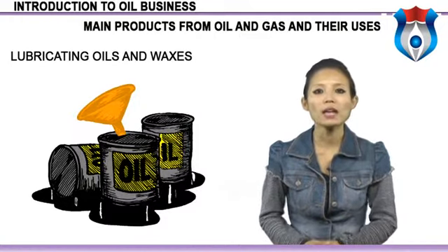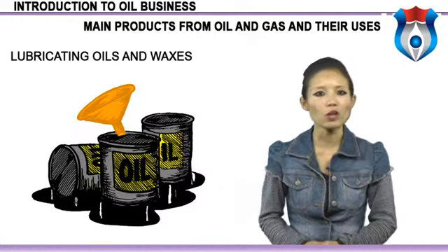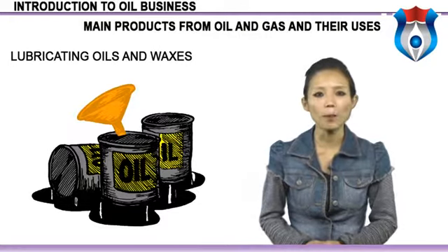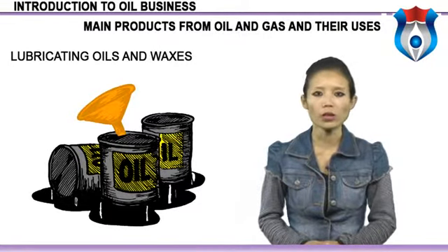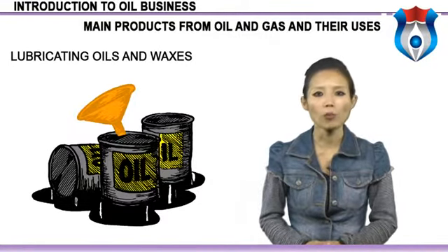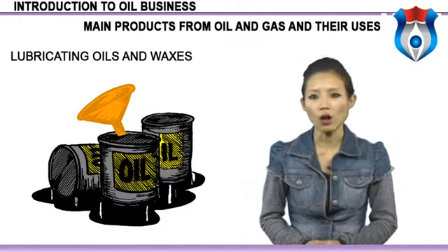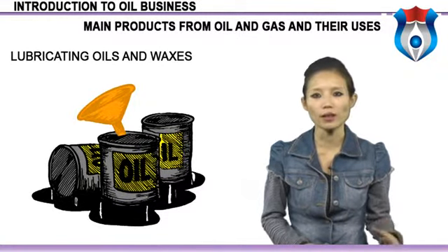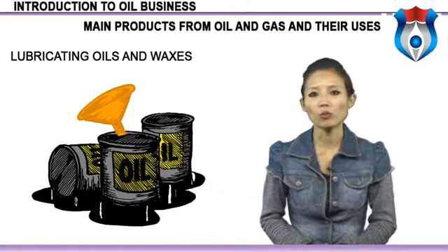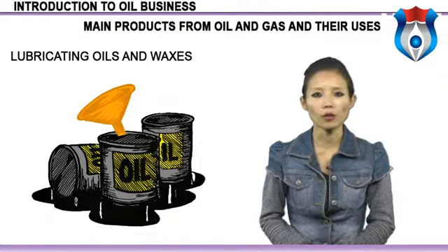The pour point is defined as the temperature at which the oil stops flowing while cooling down. Straight chain paraffins increase the pour point, while branched chain hydrocarbons, cyclic compounds and aromatics lower it. Waxes can be removed with solvents to lower the pour point.